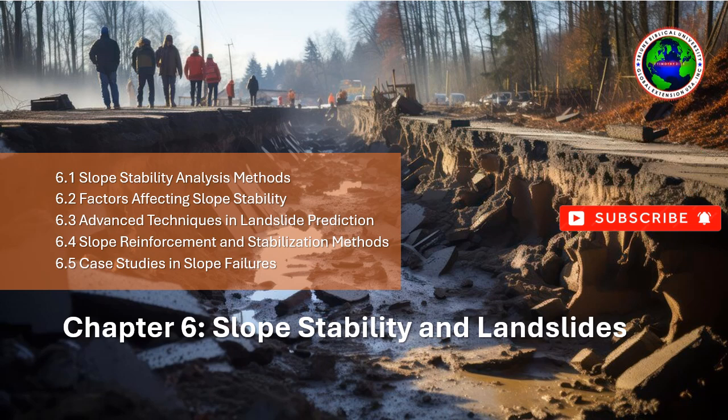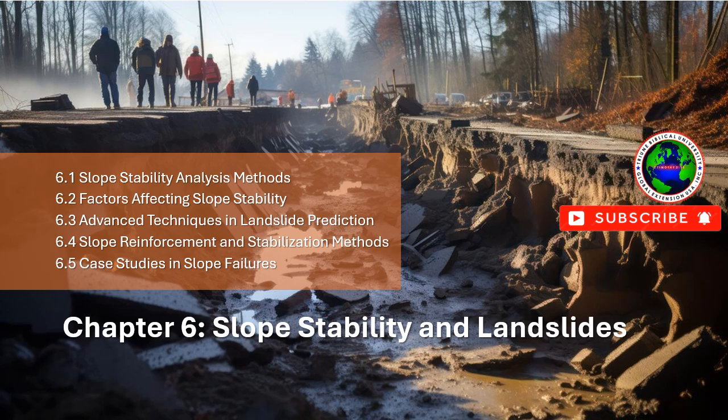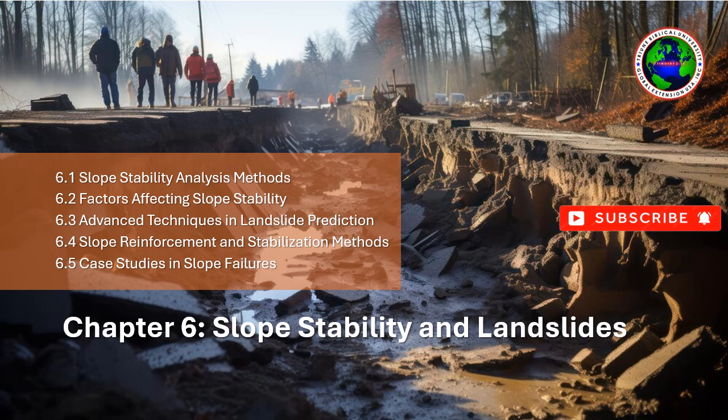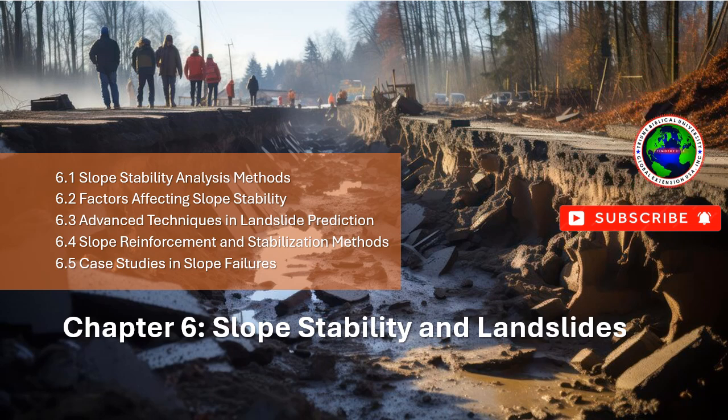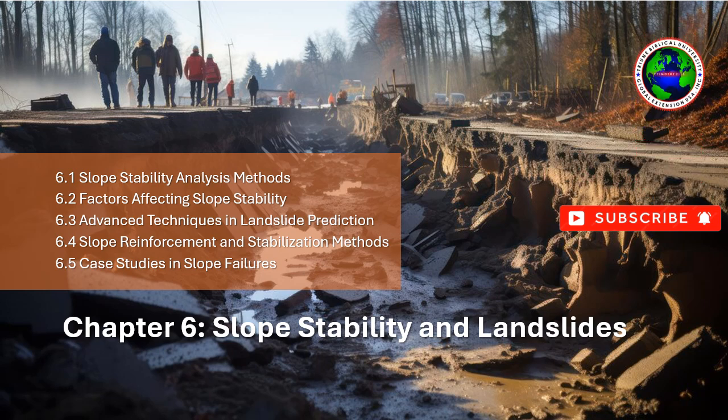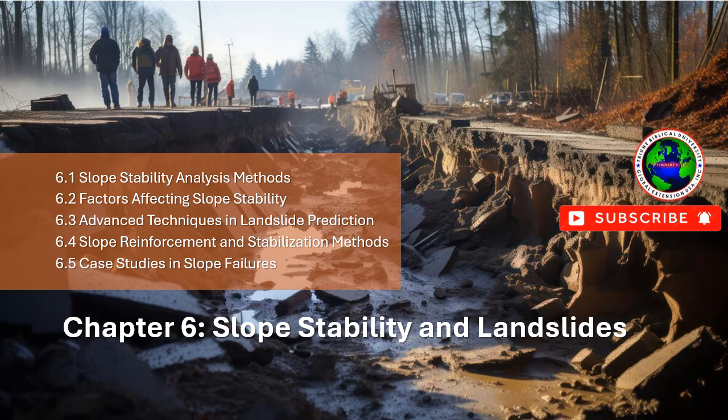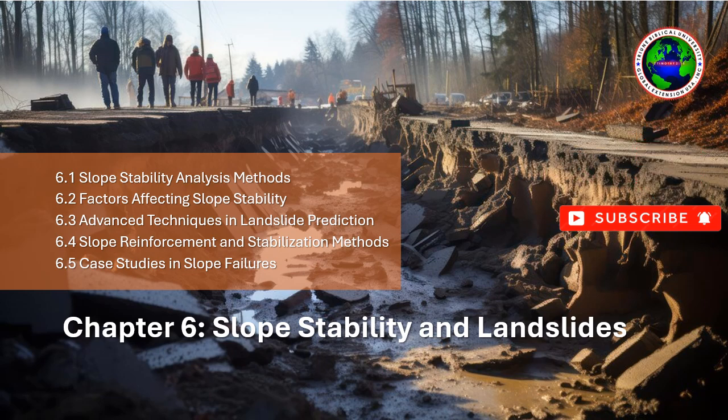mitigation if necessary. Lessons learned. Detailed site investigation and ongoing monitoring are crucial in areas prone to slope failure, especially those with complex groundwater conditions. Heavy rainfall and groundwater movement should be considered as key factors in the design and analysis of slope stability. Early warning systems can help mitigate risks to infrastructure and public safety.